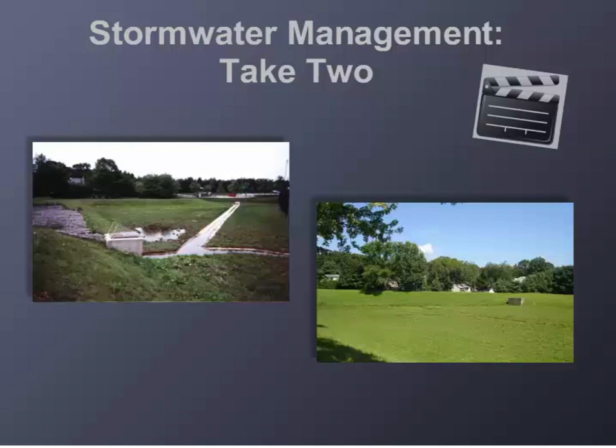But this system has limitations too. Basins are not well suited to managing runoff from smaller storms, as they directly discharge the stormwater runoff to nearby streams, waterways, or municipal storm sewer systems. Additionally, water is leaving the area and not being recharged or returned to the ground as clean water because these systems tend not to infiltrate.